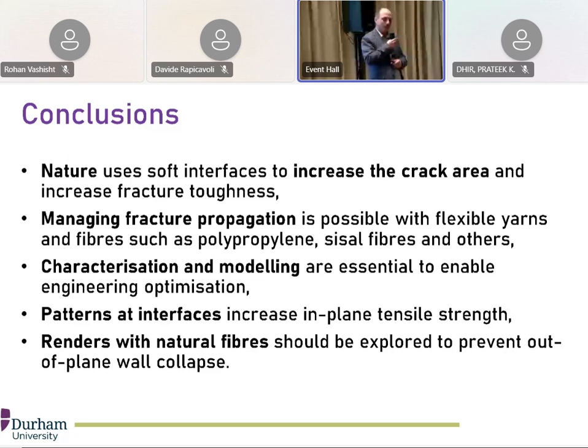And the other aspect I like about this is that renders can be easily replaced after each earthquake. If they crack, it's like a windshield in a car that is completely micro-cracked, you can just replace it with a new one. It's not a major intervention. So it effectively could become like an energy fuse. But again, I don't make a statement that this is a proven solution. We definitely need to explore it and find out for sure if it works or not.